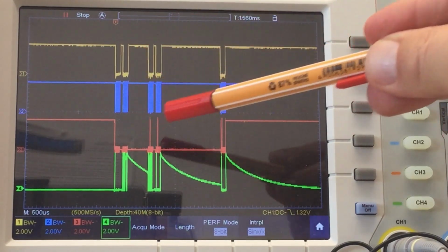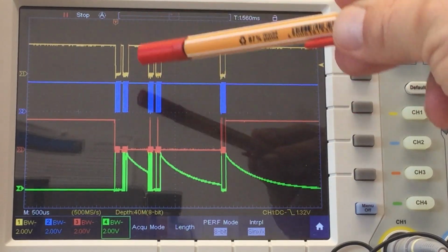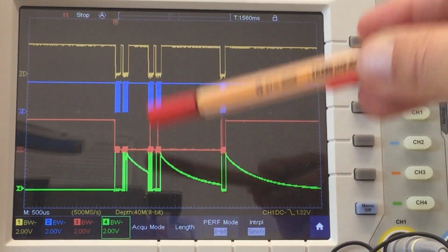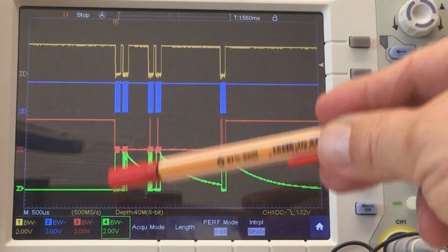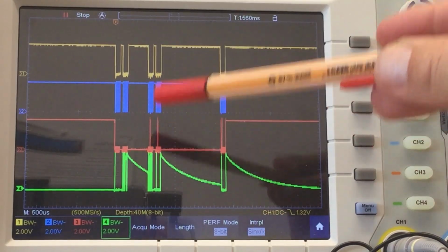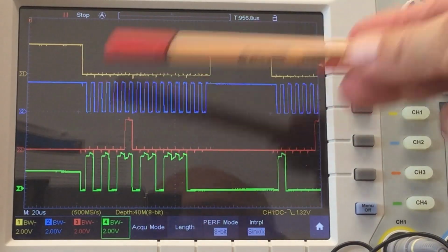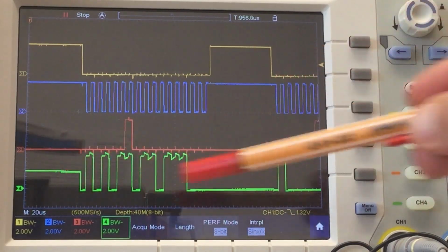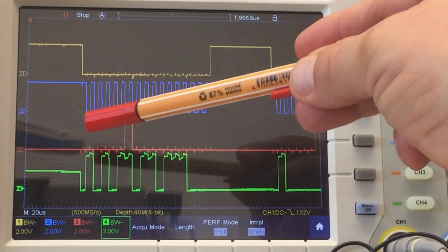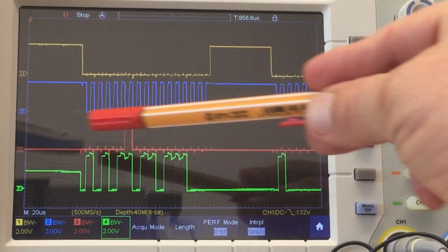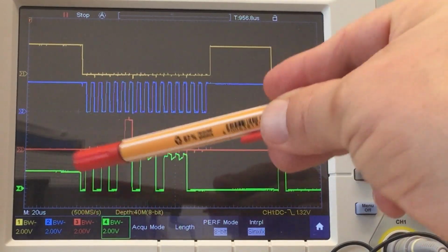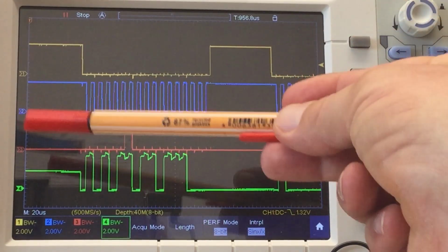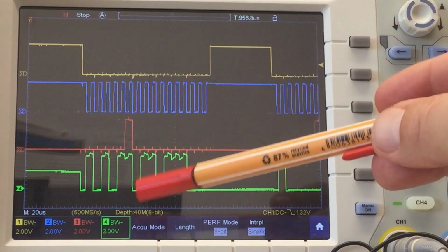Now we have a look at these 2 SPI transactions, and you see I actually sent here a different command. Now I'm reading, since I know there is some error, the error register. And that is a very good example of how the chip returns data for the last command received, because what's returned here is basically the angle register, because the last command I sent was return me the angle register.